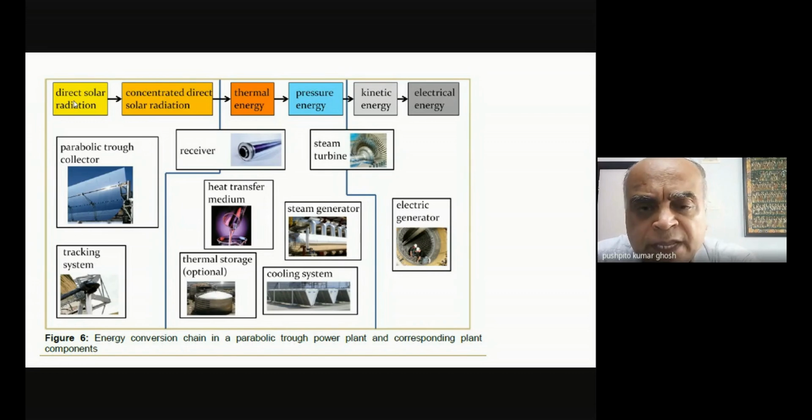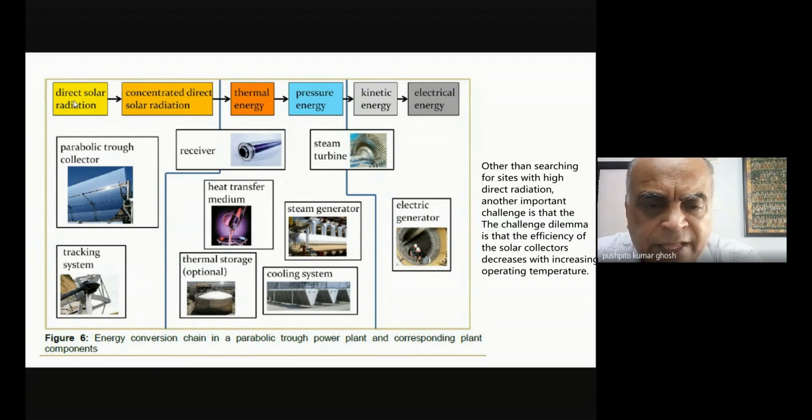What it also means is that if you are trying to set up a unit, let's say somewhere in India, and you say I'm going to set up a solar concentrator, you better know what kind of ambient atmosphere you have, and if it is very dusty, you measure the direct radiation and the indirect radiation, and see whether this looks like something that I can do.